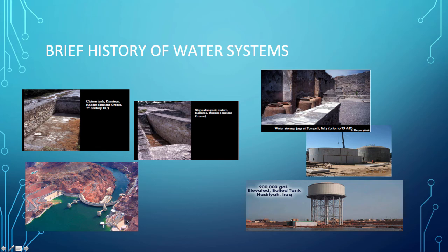This big hole here is the emergency overflow spillway, and there's another one here. And then this linear feature here and the one you can't see here are actually side flow weirs. So if it looks like the lake is getting too full of water, these weir gates can be dropped a little bit, and the water flows over here and then goes through the hole and comes squirting out down here.